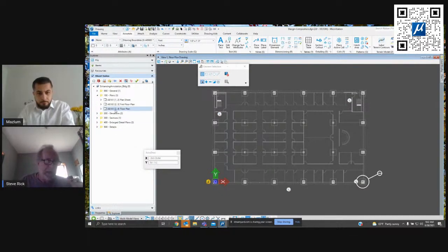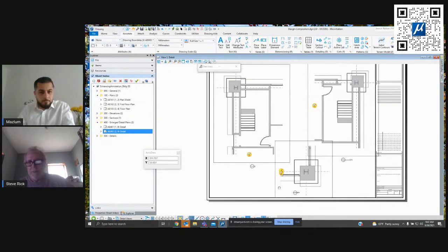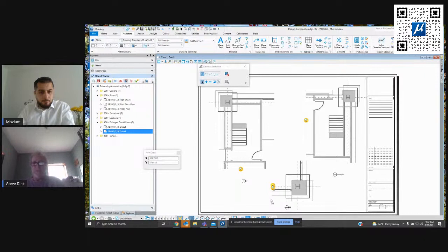Okay. So if I want to go back to my detail plans, here's my AE 402. I can just double click here in the sheet index and it will bring me back to my detail plans, right? So 3 different details. Again, remember, this was really hard to do in the past. Putting multiple details or multiple drawings on a sheet and calculating scales was incredibly laborious.